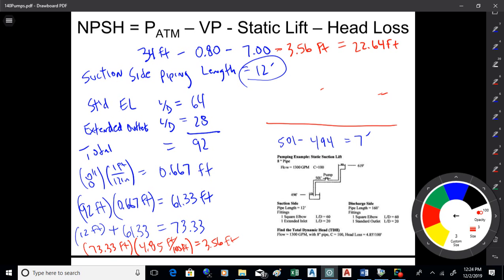Now, I got some pump curves, which we'll get to probably Wednesday, but if you look at the one on page 153, you'll see over there on the right how they have NPSH listed for that pump curve. What they're doing there is telling you, for whatever condition you're pumping at, here's how much NPSH you need, okay? So this is a number you do pay a little bit of attention to if you're lifting the water out of a reservoir.